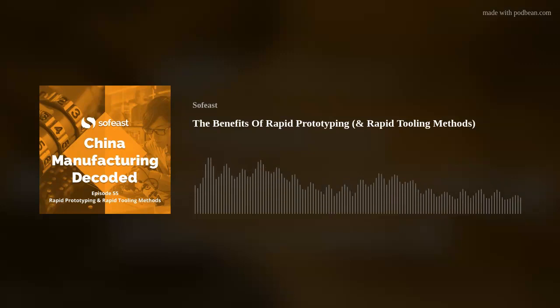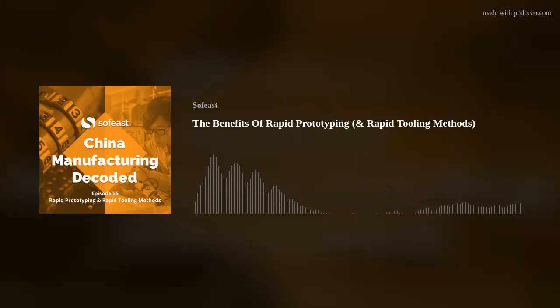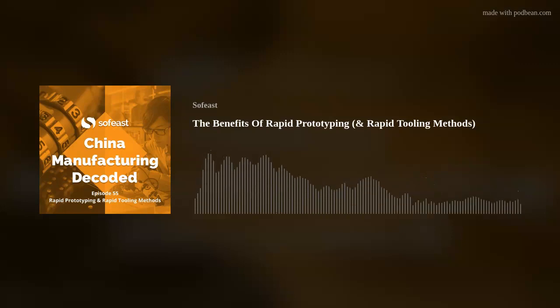You know, every time making adjustments, fixing, because they typically make the mold a little bit larger, meaning that the parts themselves will be a little bit smaller, because they stay metal safe or steel safe, meaning that it's always better to make the part a little bit too big, and then adjust by removing some of the material from the mold. But if you make the part too small and then you need to add, you need to go into welding to add some material. It gets messy, and it really has an impact on the lifetime of the mold, right?